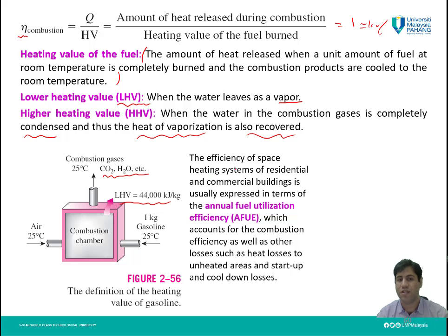But usually the efficiency of space heating systems of residential and commercial buildings is expressed in terms of the annual fuel utilization efficiency, or AFUE, which accounts for the combustion efficiency as well as other losses such as heat losses to unheated areas and startup and cool down losses.